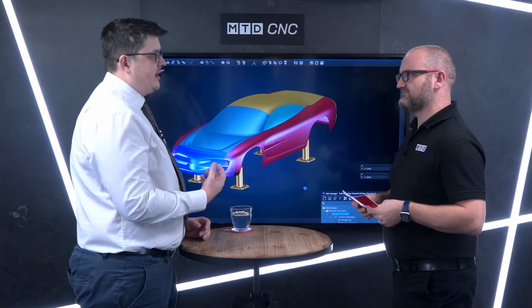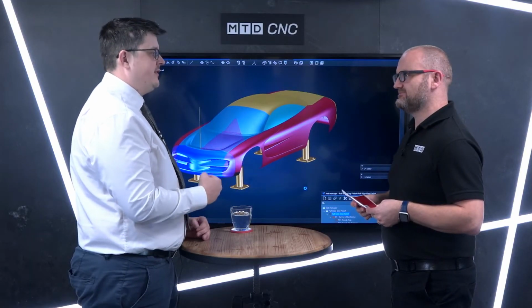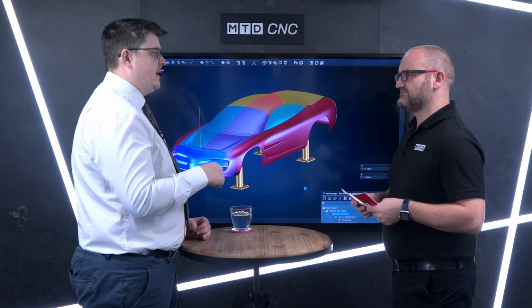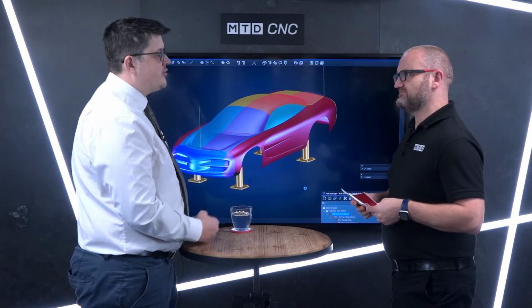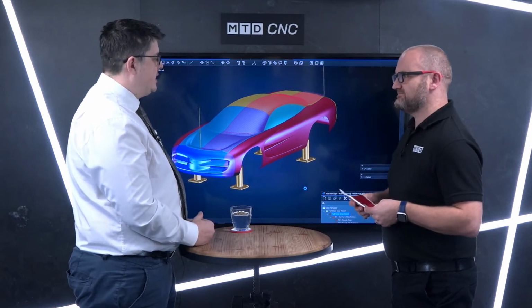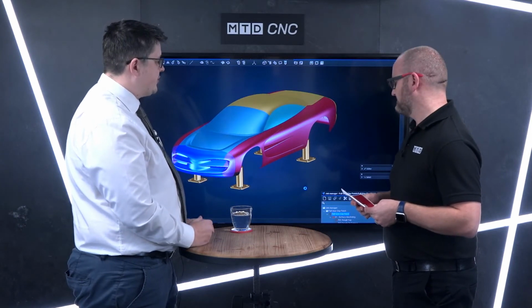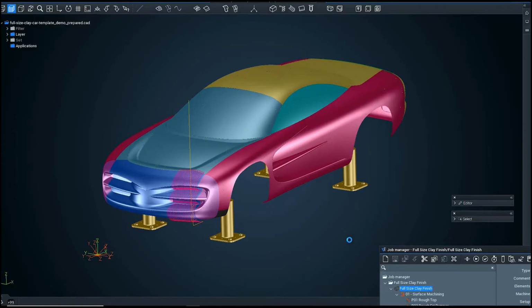Absolutely. Tebis is able to automatically create 5-axis toolpaths within these templates. In the first model that we saw, we had a 3 to 5 axis converter, and that is literally creating a 3-axis toolpath, converting it to 5-axis, and that just to create tool holder clearance on the tool as it's machining down steep sides. In this particular example on the screen, Tebis is also able to determine that it's a 3+2 operation that's needed, and changes the tilt angle of the head and creates the correct approach positions and directions for the tool. And that's defined by Tebis.